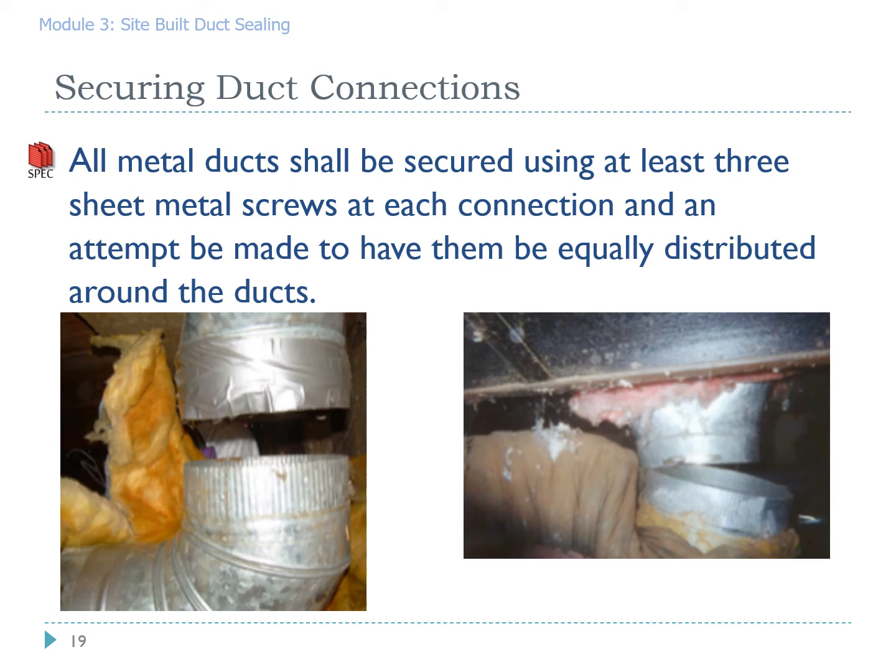As we've said earlier, mastic is not magic. Yes, it can seal a ductwork for life, but unless you've mechanically fastened the system together, no amount of mastic is going to make it permanent. Once again, remove the duct tape or any duct tape around it, connect the two pieces together, try to get at least 3 screws evenly spaced. We realize that sometimes you can't get to the back side of that ductwork, but generally you can get enough screws evenly spaced that you've made a secure connection.